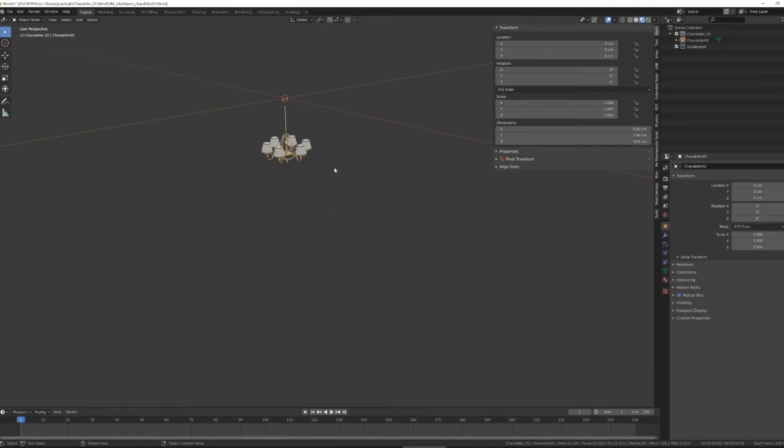As I'm renaming all of the objects in my file, I also want to double check and make sure that they're using the correct scale factor. To do that, if I select an object and go to the Item tab on the right here, I can see that its external dimensions in the Z direction are 10.8 centimeters, which is too small. So I can either set dimension here, so I can set my Z height to be what it should be, which is 1.08 meters.